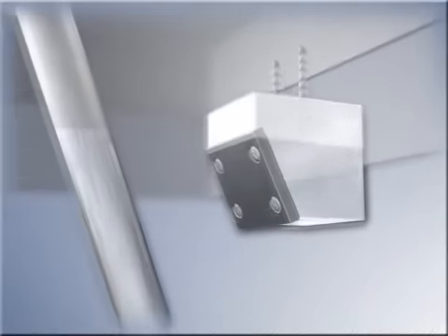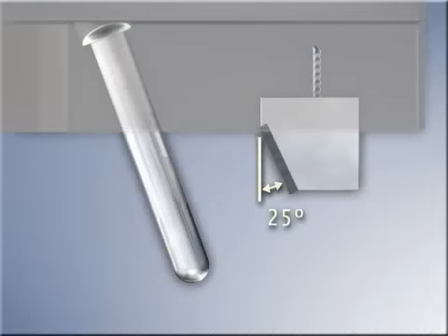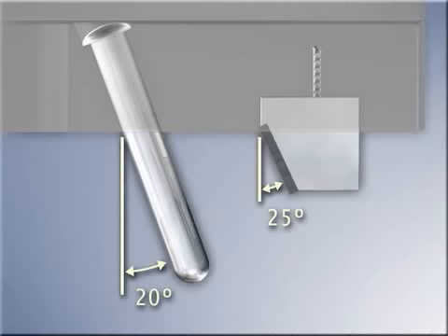If actuator pins are used to push the slide forward, the angle of the slide lock should be approximately 5 degrees higher than the angle of the actuator pins. This is done to minimize the force applied to the pins.